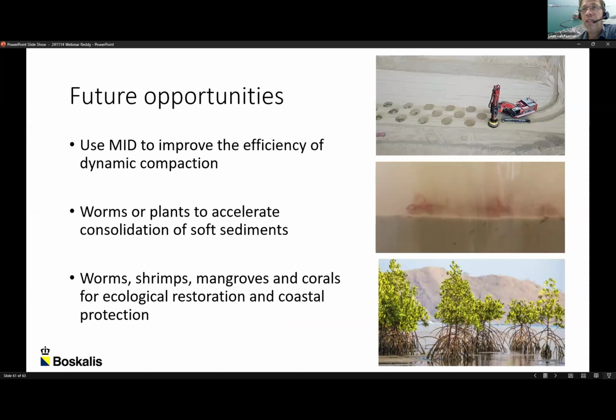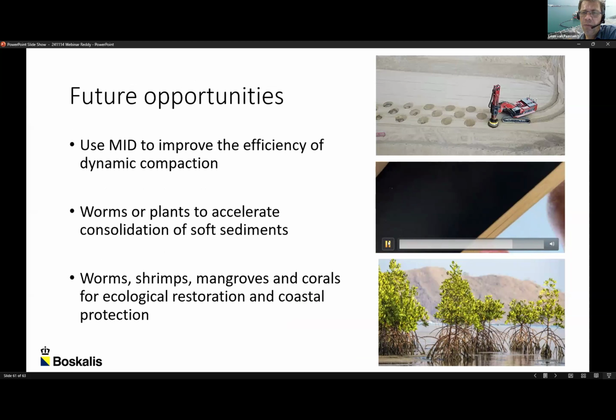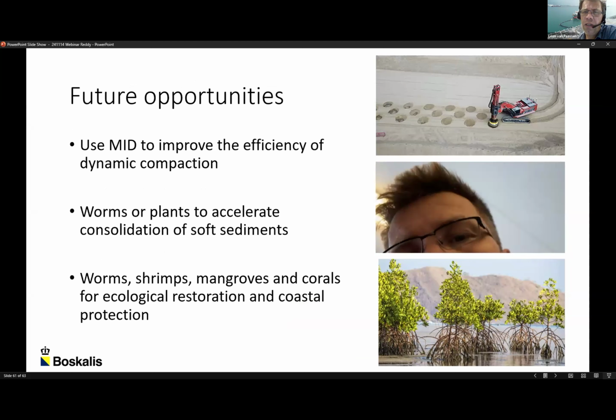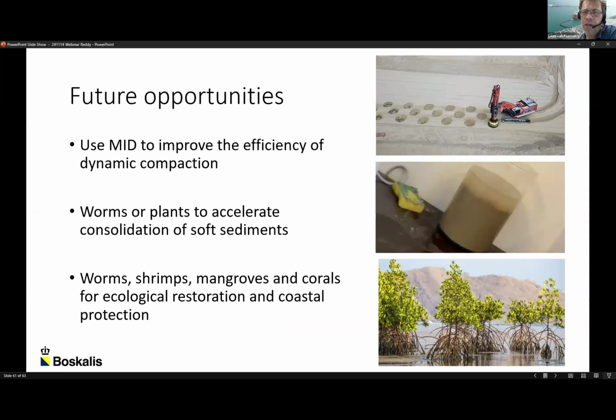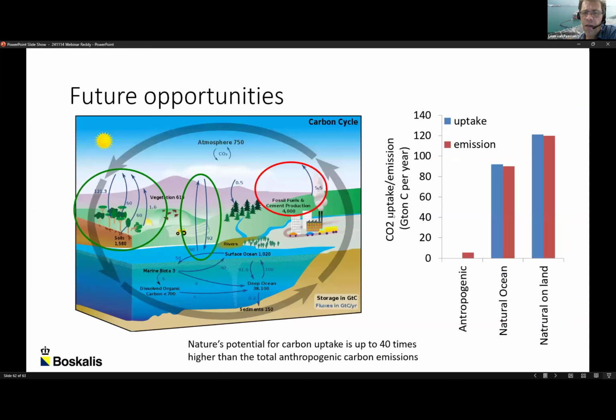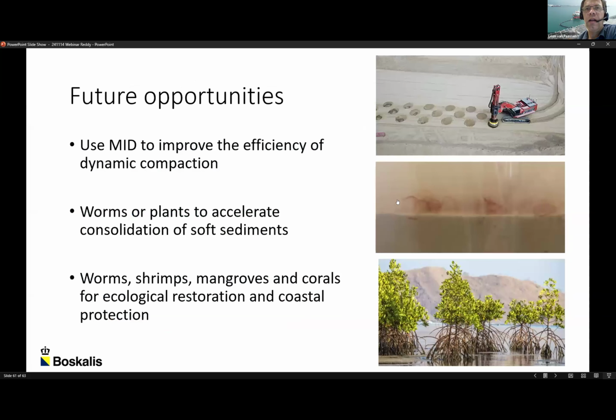And the process of denitrification and precipitation has a competitive advantage for places where there is already existing infrastructure, but if you have a plain field, then still dynamic compaction or rapid impact compaction are often economically preferred over any type of cementation or in situ treatment method.